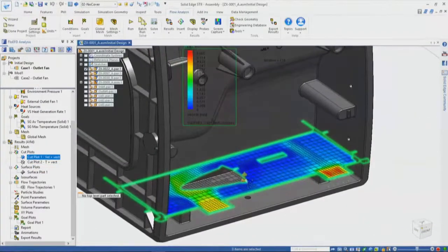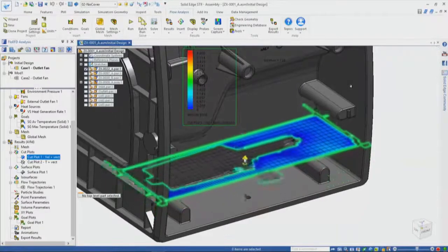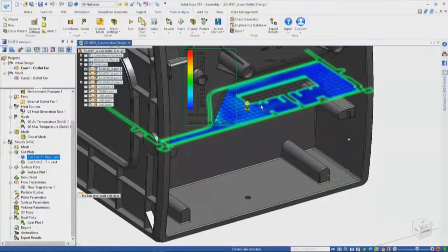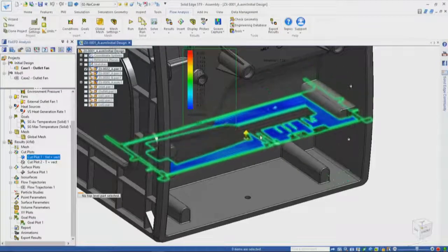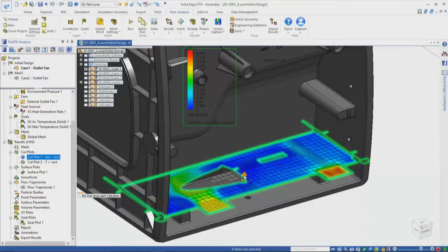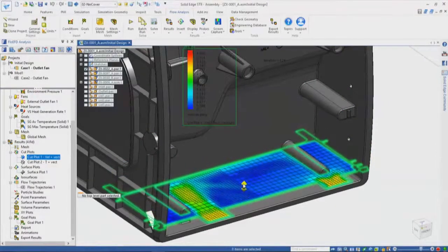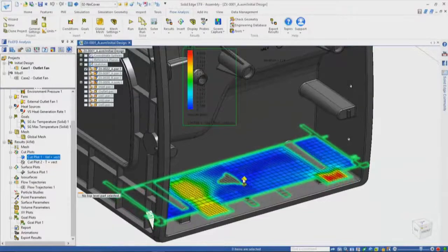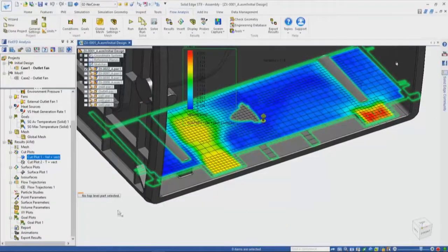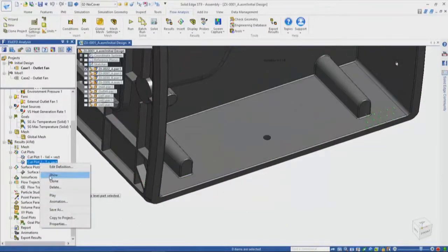So I'm going to start with a cut plot. And on it, I am going to show the mesh just because we didn't get a chance to do that part of it live, although this mesh took about 1 to 2 minutes to run on Doug's Surface Pro over here. So what I'm showing is the solution. This is the velocity, so this is the speed of the airflow, and overlaid also with what the mesh looks like through here. And you'll see that both the fluid region as well as the solid volumes are meshed in this one continuous mesh to get this conjugate heat transfer problem. You don't see a solution in the solid part right now because that's velocity that we're looking at.